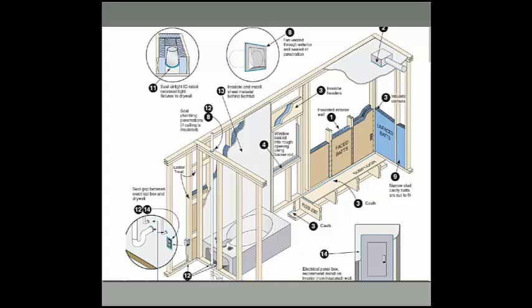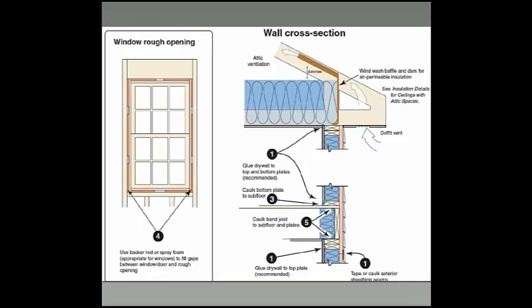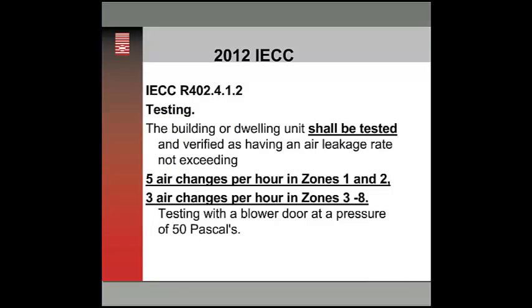It's going to be around plumbing vents, B vents, electrical penetrations, just the normal laundry list of bypasses that leak up into an attic space. Obviously, under knee wall bypasses on some of these buildings can be a big leak, and here are some more diagrams showing some of these air leakage points, the likely suspects.